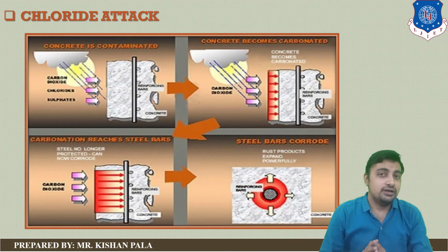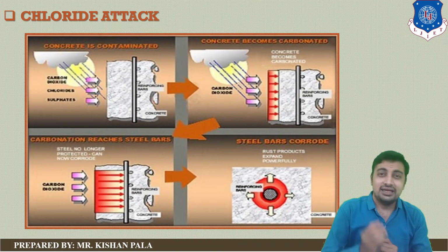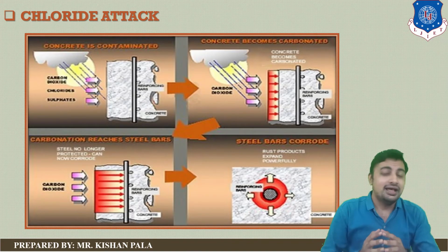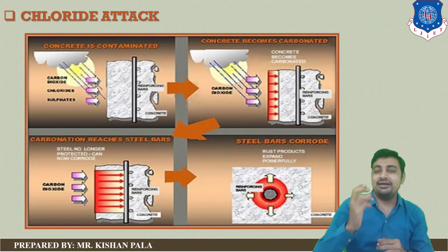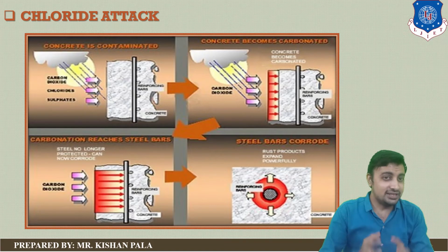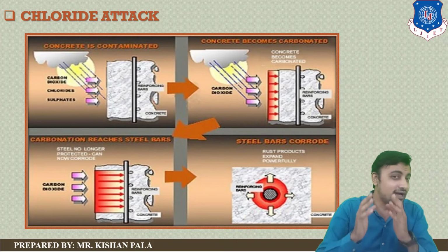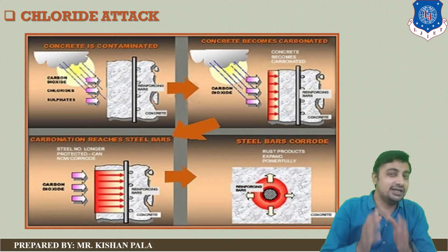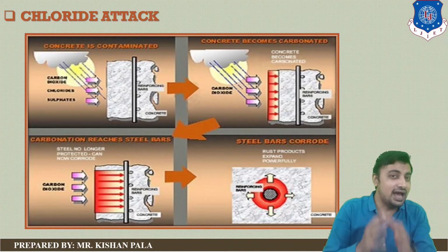If we talk about the effect of de-icing, the salts normally used are sodium chloride and calcium chloride, and their repeated application with freezing or drying results in surface scaling of concrete. Sometimes urea is used to remove the ice, and it is less deleterious but also less effective in removing ice.